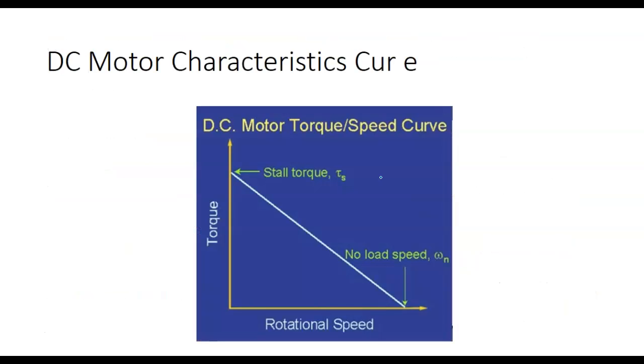Yeah, industry standard is to switch 1 and 3. You can switch any 2 phases, and it changes direction. But industry standard is to switch 1 and 3. Why do you want to follow industry standards? If somebody else comes in there and works after you, right? They know what to expect.